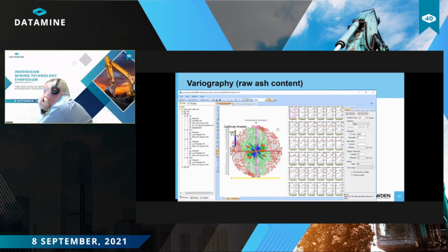This means that all gamma values from the variogram have been divided by the sample variance, and therefore the variograms obtained on the right-hand side here are all directly comparable with each other.